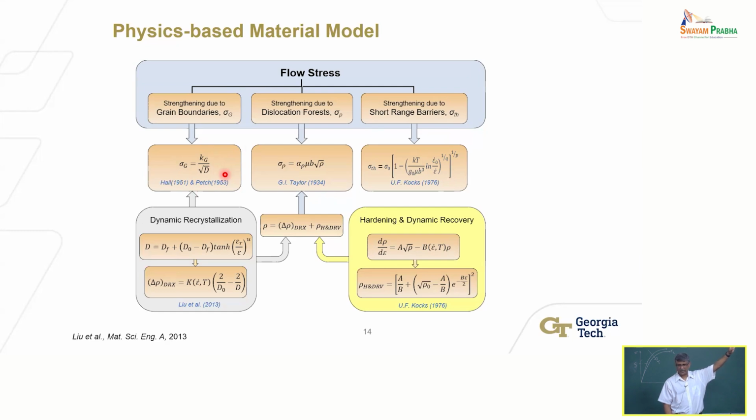You have come across that Hall-Petch relationship. That's an empirical relationship, really. It describes that if I have more, smaller grains, which means many grain boundaries, obviously the strength will be greater, up to a point. There is also something called an inverse Hall-Petch relationship that I'll talk about later on. So this is all happening. These equations allow me to describe that. I can add all of them up, but it's more complicated than that.